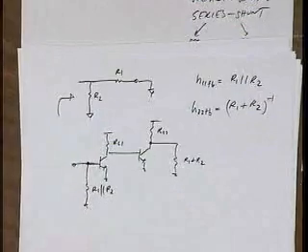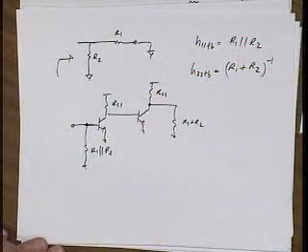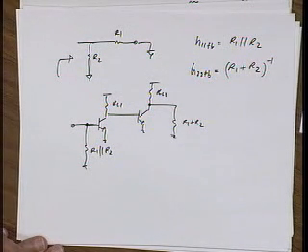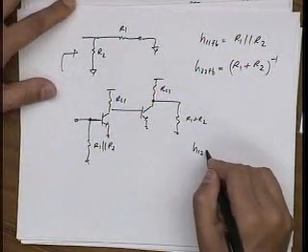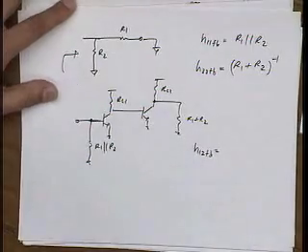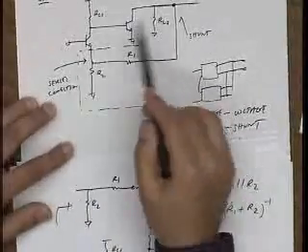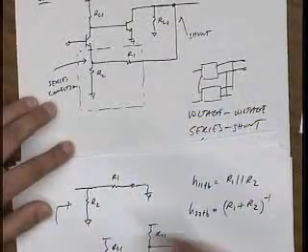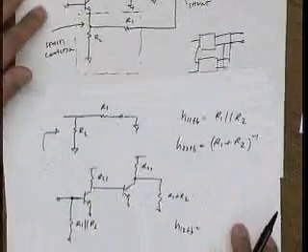Okay, that's really nice. What's the loop gain? Of course, we need to calculate H12. So H12 of the feedback network. Let's neglect H12 of this amplifier, right? It's a two-stage cascade. There's very little feedback in 2 stages. Okay, especially at low frequencies.